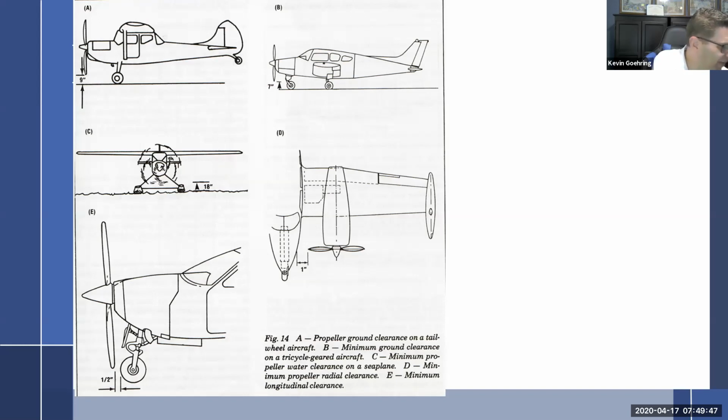So I guess I'm telling you all that because one of the problems I have, as a guy who made a living doing prop strikes, is to land an aircraft in what they call a wheel position. So if you look at number A right here, this was landing, doing a wheelie landing is what they call it. If you do a 3-point, you actually land it with the tail wheel kind of hitting at the same time. And I learned in the Cessna 140, which was a terrible wheel landing plane. But what you have to do is you come in, and as the wheels touch, you have to go hard forward on the stick to keep those wheels planted.